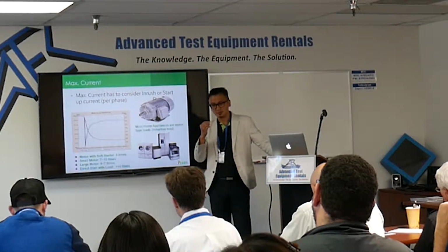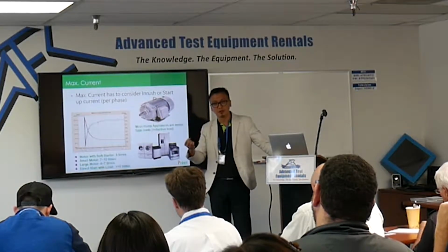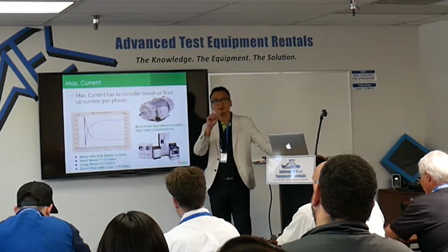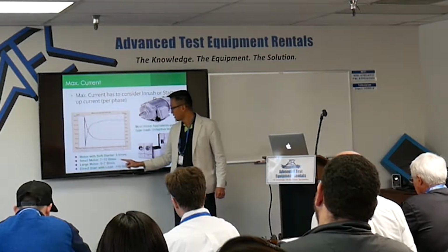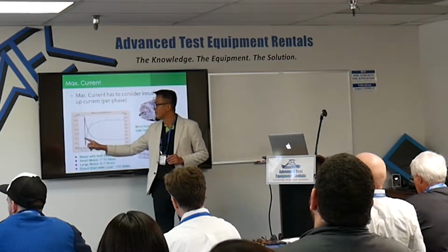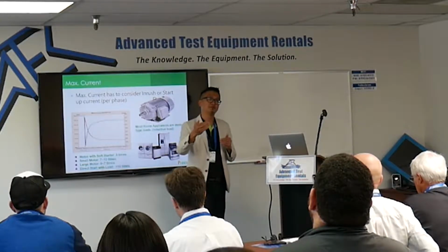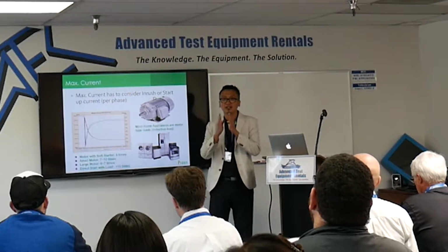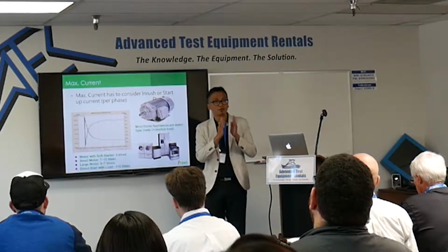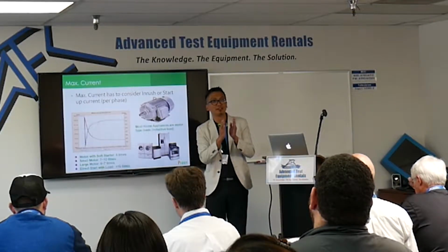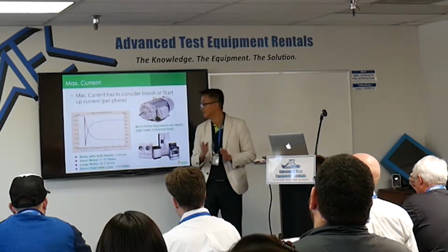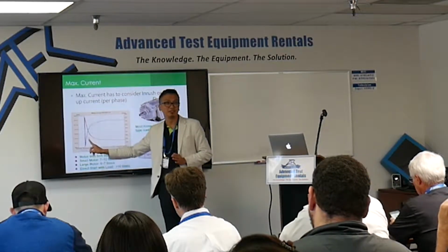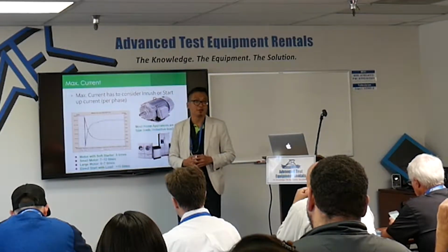They can sustain a certain overload capacity. When you read the power supply spec, you can check the overload capacity. Overload capacity means the power supply can sustain like 150%, and some power supplies can sustain 200%. But also read carefully the duration. The power supply will tell you, I can handle 200% for 30 seconds, or for 1 second. But you have to check how long your inrush is. If your inrush is within a couple of milliseconds, it's fine, or within 1 second is fine.